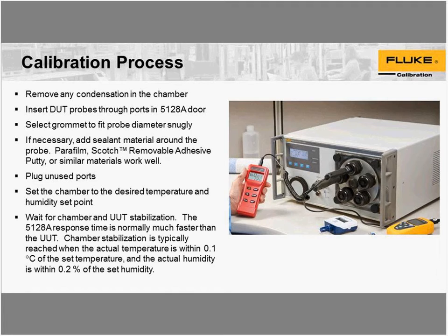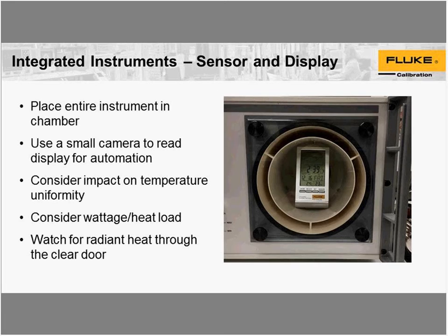And here's a method of calibrating integrated sensors and units. Sometimes people call these pucks. The entire unit goes inside the chamber. One thing to watch out for here is that sometimes the displays can put off some heat, so they can be tricky to calibrate. So be careful with those.